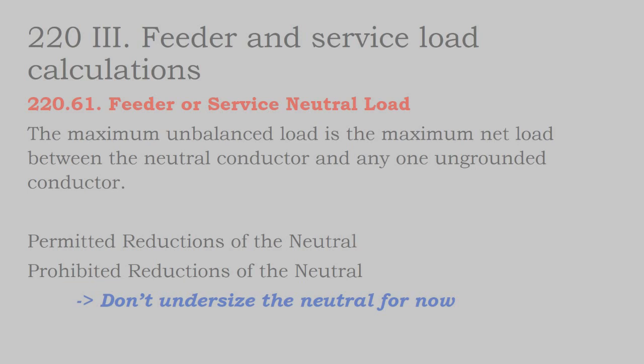If you do all of your conduit calculations for a full size neutral, you're not going to have any design changes if, when it comes time to order the material, your supplier comes back and says, well, actually, you usually undersize the neutral in this location, and you decide to do a design change. But if you're just beginning, don't undersize the neutral for now.